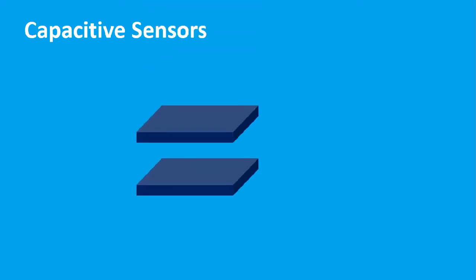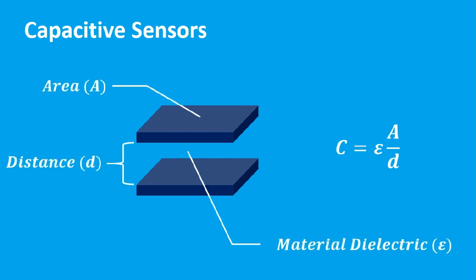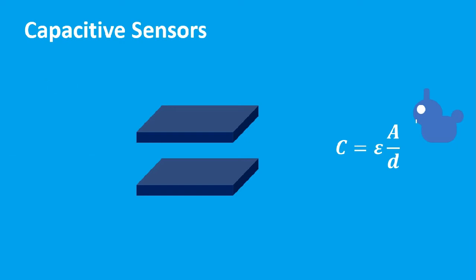Basically, capacitive sensors consist of 2 parallel metal plates in which the dielectric between the plates is either air or some other medium. The capacitance will change if any parameter changes. An application for capacitive sensors is pressure movement, in which the movable capacitive plates relative to a fixed one changes the capacitance. In this example, the decrease in distance resulted in the increase of capacitance.